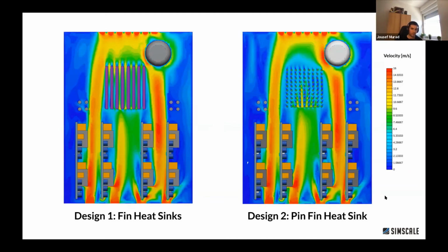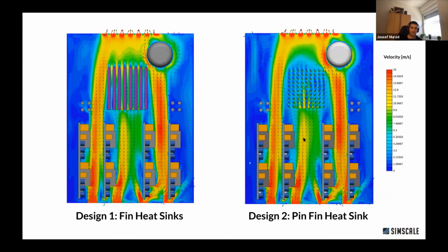To have a look at the flow field, you can immediately see how the flow field changes, if there are any blockage effects or maybe some recirculations. It cannot be investigated that easily if there are any recirculations. So what you usually do is impose a vector field and see if there are turning arrows to investigate if there's a recirculation zone. If that would be the case, you have the option to redesign your component or replace the components and easily run another iteration in parallel.